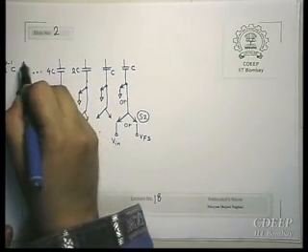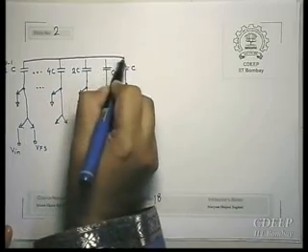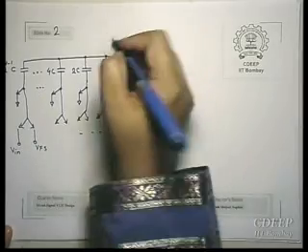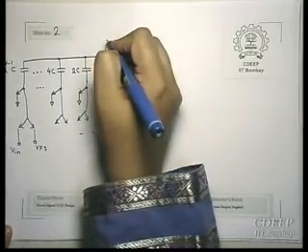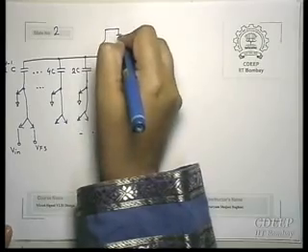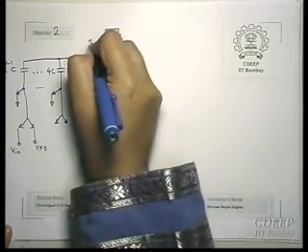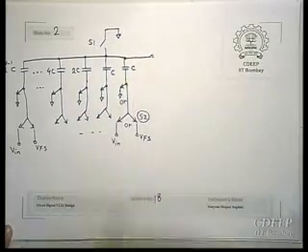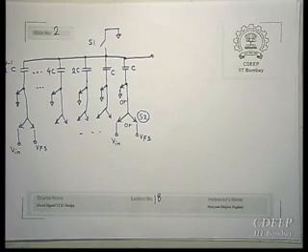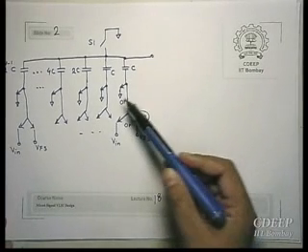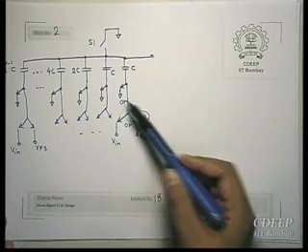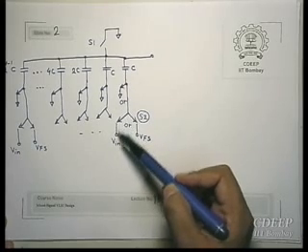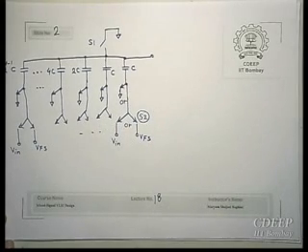And then the upper plates are connected the same way as in the passive charge scaling, and then you have a switch S1, and this was the output. Now we have a sampling switch which also allows us to sample the input voltage on the capacitors.